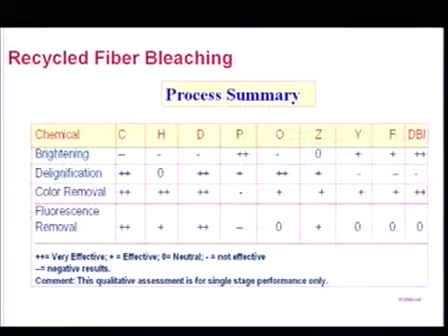So, if you have a lot of mechanical pulp, you need a brightening process. So, what are the chemicals we can select? I would select peroxide because it is a nice brightening chemical, very effective. Then I can select hydrosulfite, it is effective. Peroxide can brighten virgin mechanical pulp up to 20 points. And with MAG, you can get up to 7 or 8 points with peroxide in brightness.